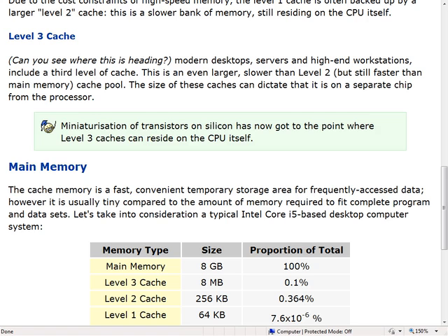But you could upgrade your 486SX with what's called a 487 processor, and that was the math coprocessor to go alongside it. And the 487 processor was a perfectly good 486DX processor with everything else except the math coprocessor disabled. So as they improved their process, they were able to make these things so reliably that, in order to satisfy all the market segments, they ended up making heaps and heaps of these really good quality chips and intentionally breaking them so that they could satisfy particular market needs.